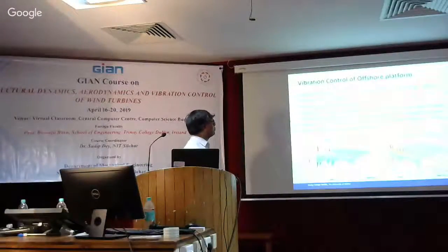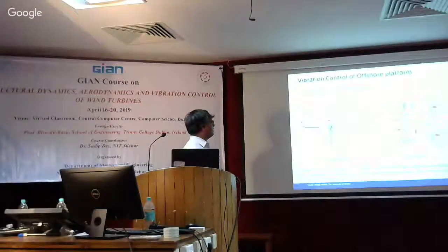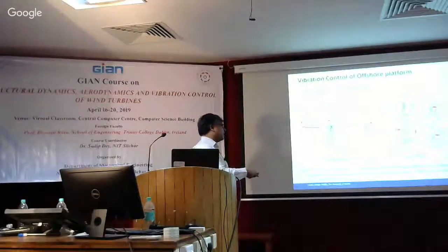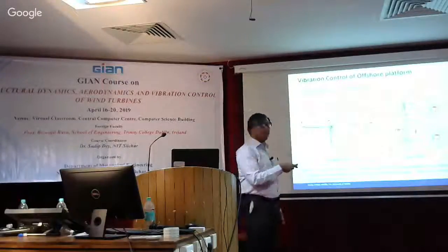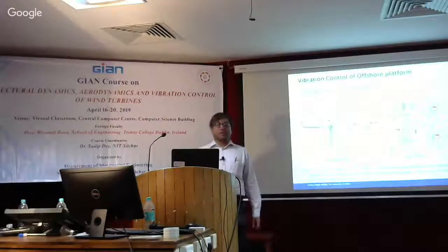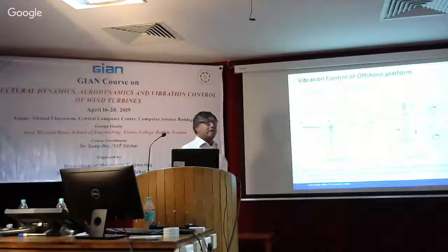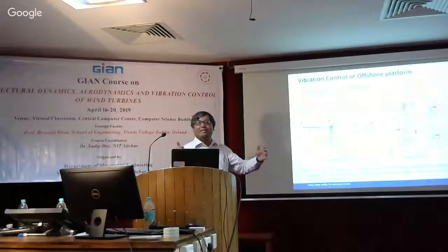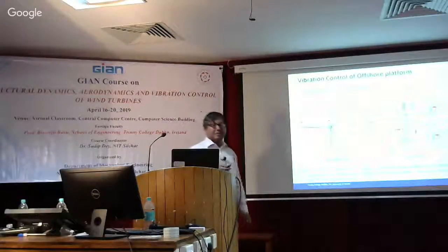This is also known to you. We have gone through these and some of the control. And this is actually one of the papers where we had a passive control of a floating offshore wind turbine. We couldn't actually control the platform motions. All we could do was control the heave motion, but the other ones we couldn't. I know people are claiming that they can do it, but it is very strange because it's a half a minute period, so you can't do it with any tuned mass damper.